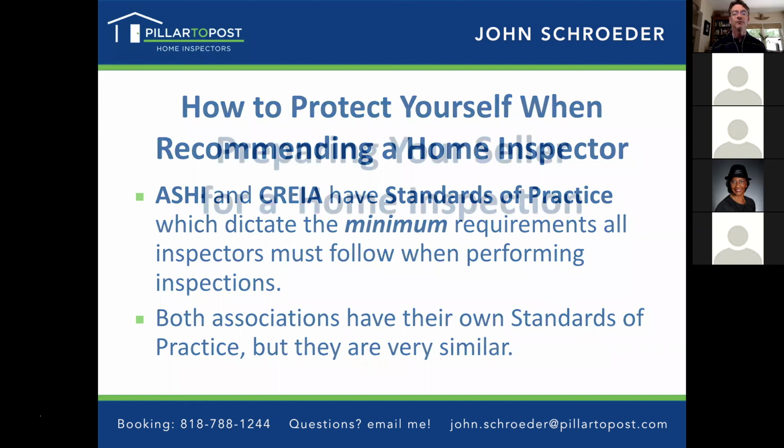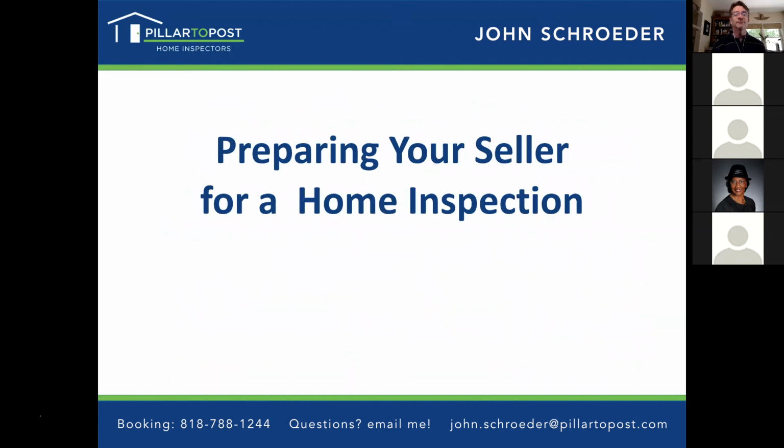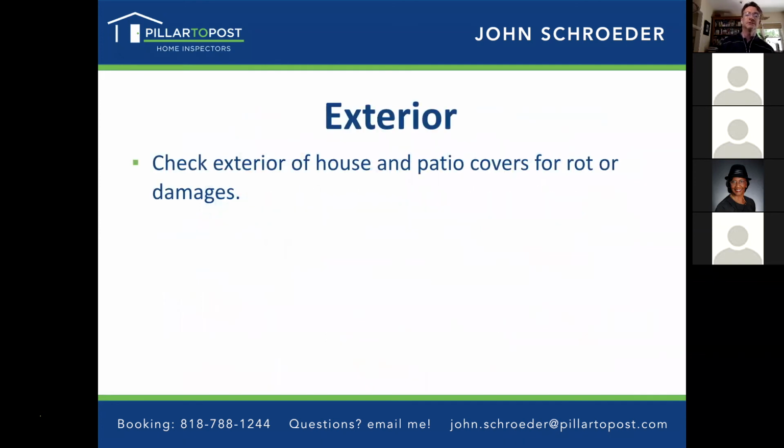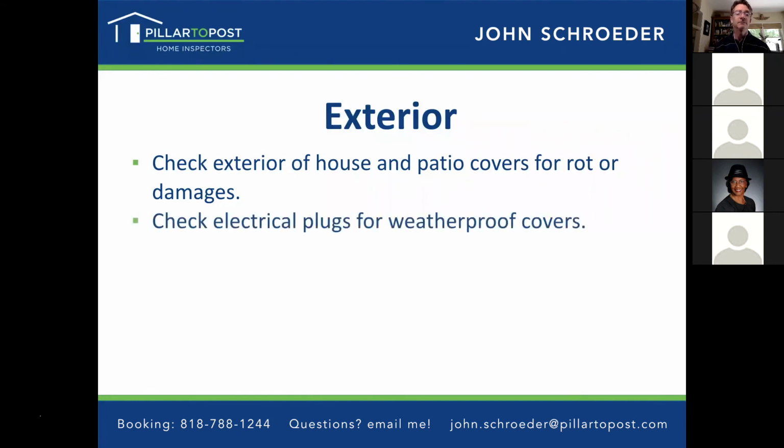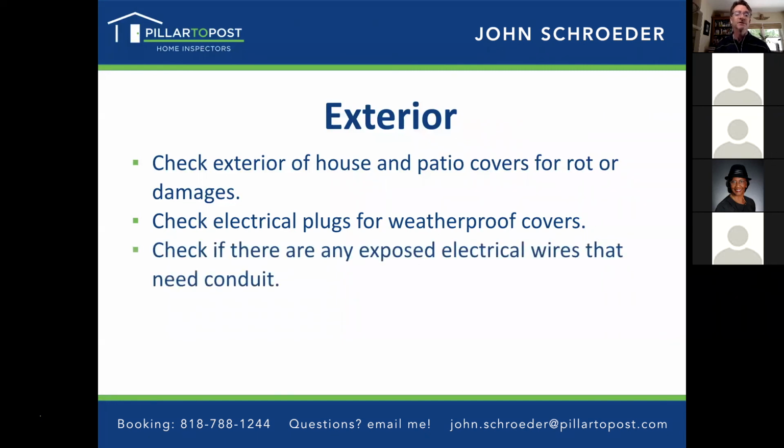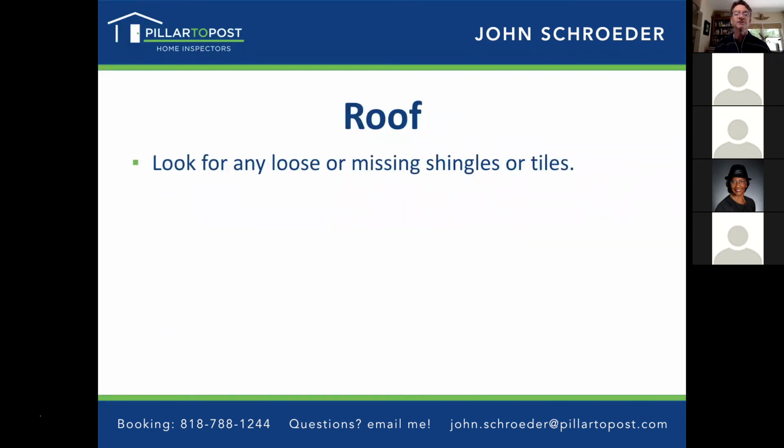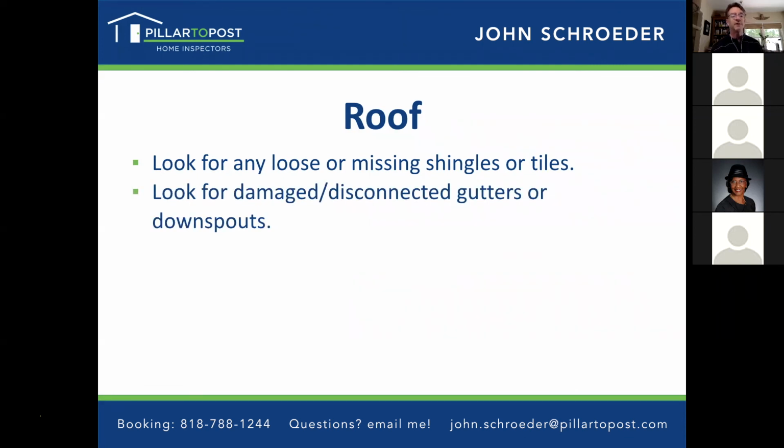So either one works. So here are some thoughts for preparing your seller for a home inspection. There are a lot of things that you can do to sort of know what you're up against before a buyer comes in and performs an inspection. So you can check the exterior of the house and patio covers for rot or damages, check electrical plugs for weatherproof covers on the exterior, check and see if there are any exposed electrical wires that need conduit, look for loose or missing shingles or tiles, look for damaged or disconnected gutters or downspouts.